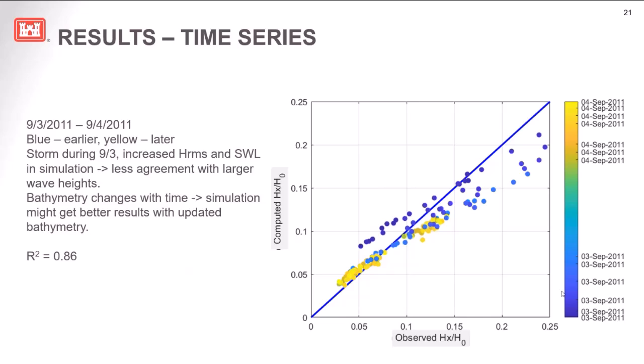So we may be able to increase accuracy using more information about the wave spectra and incorporating this into the calculation of energy dissipation, because there were some bimodal waves present, but we're currently just using representative wave properties such as the peak period and wave height.